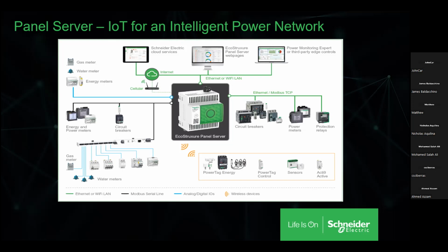It's simply like any gateway that can convert from Modbus serial to Modbus TCP/IP. This is the same gateway, however, we have added some additional features. It can convert from Modbus RS485 or Modbus serial to Modbus TCP/IP. It can convert from Modbus TCP/IP to TCP/IP. It can get ZigBee communication protocol devices, what we have presented in our session today.